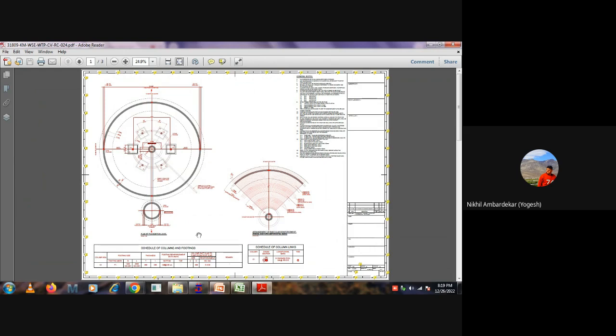Okay, so if you need, say, a 300 thick wall and the internal dimension is 5 meter, and you take the wall thickness inside, then 300 from here and 300 from there, how much is that? 600. So you cannot go with 4.4 meter, because again you are reducing the volume of the water. Maybe it affects the hydraulic flow, those things. So basically geometry is defined by the process engineer in the industry.